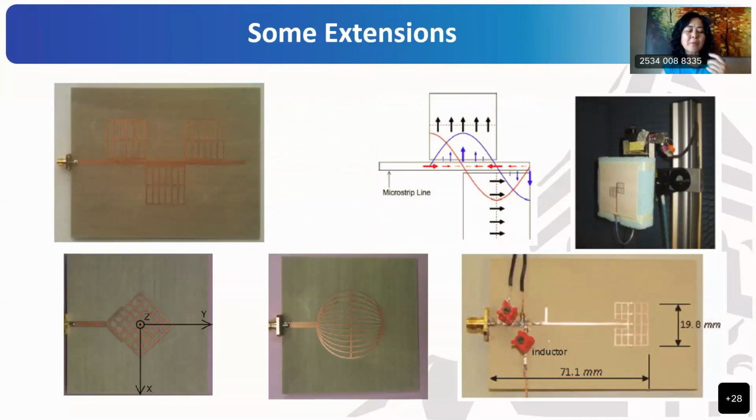All right, so a byproduct here, when we study the meshed patch antennas so that they can be made transparent and put on the solar panel, we also found something that we can play with. My students found out that for the meshed antennas, we can assemble them like the first picture on your left. We can assemble them smartly to increase the bandwidth of an antenna. So now we have an antenna with a longer bandwidth and it's still transparent. We can put it on a solar panel, okay? And that feed line can always be hidden or embedded in between two solar cells, so it doesn't block solar cells.